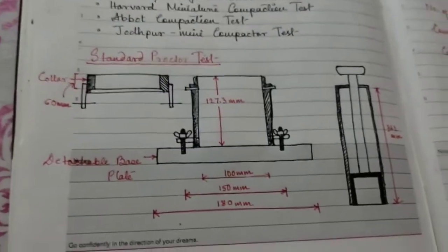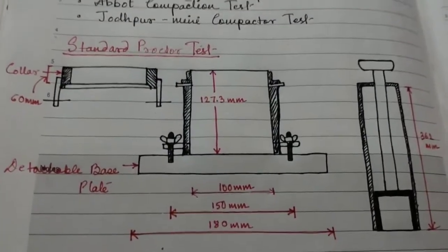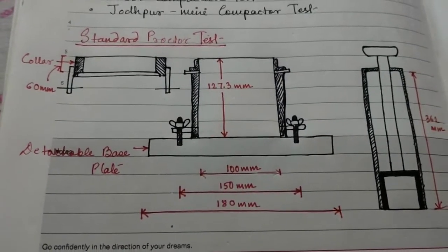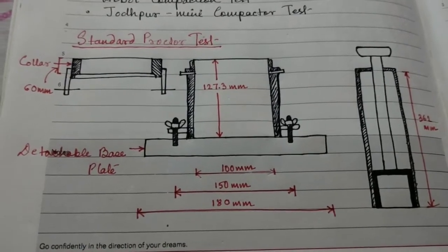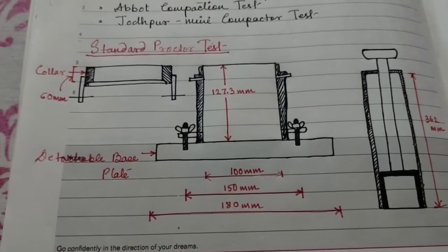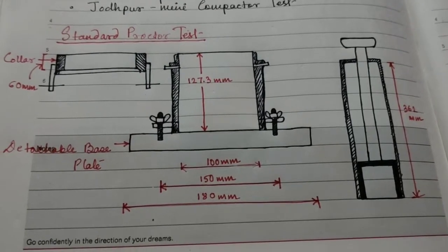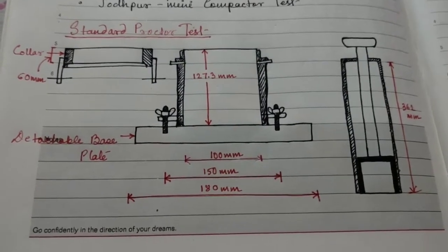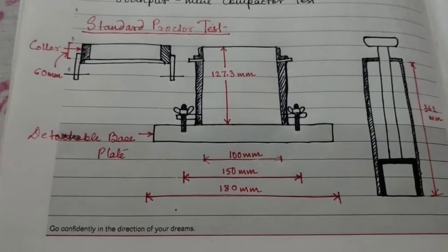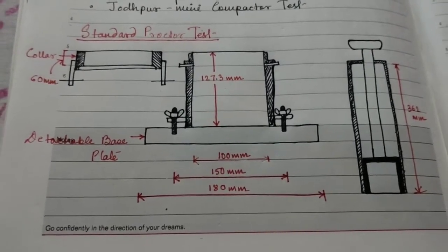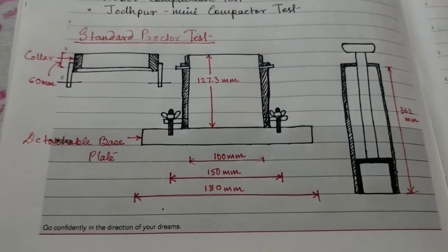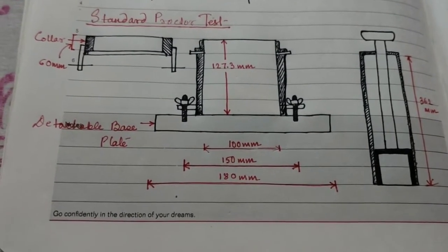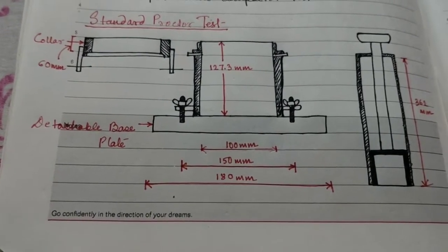You have already gone through the previous soil mechanics unit on how to calculate the water content. As you already know, the water content can be calculated from a simple laboratory experiment, that is the oven dry method, or in the quickest way by the calcium carbide method. But for accuracy, we mainly go for the oven dry method, where a sample is taken, weighed and then placed in an oven for 24 hours.